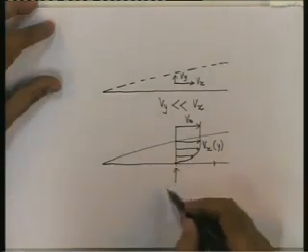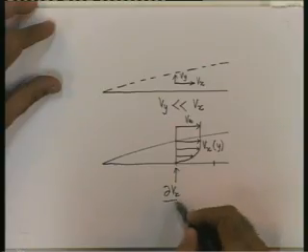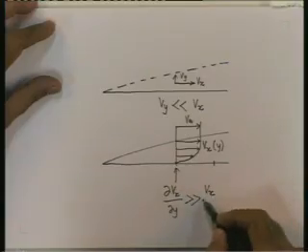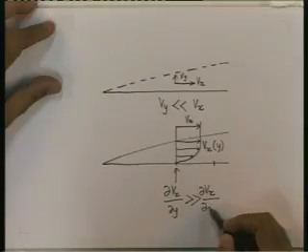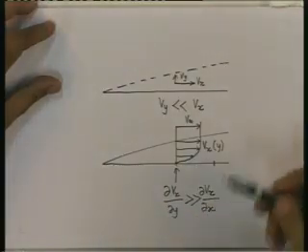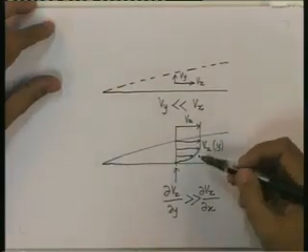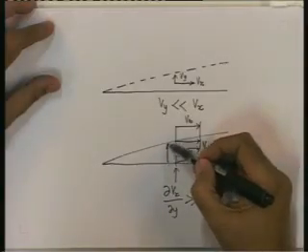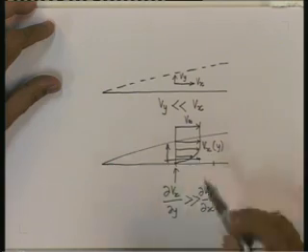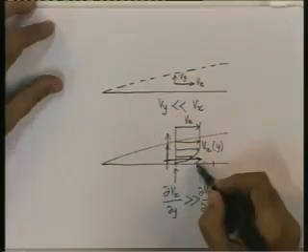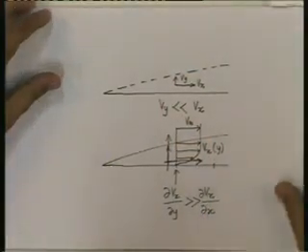If you consider the variation of Vx in the y direction, that will be much larger than the variation of Vx in the x direction. Since the gradients of Vx and even pressure, temperature, whatever, are higher in the perpendicular direction than in the flow direction, conduction of heat and diffusion of momentum would all be significant in the y direction, that is across the boundary layer, than along the boundary layer. This is a major characteristic of the boundary layer.